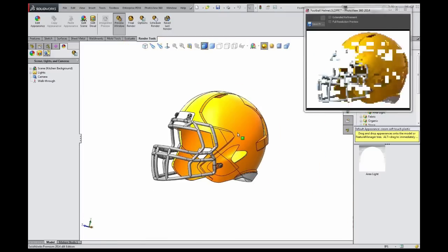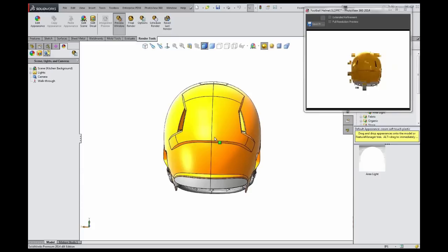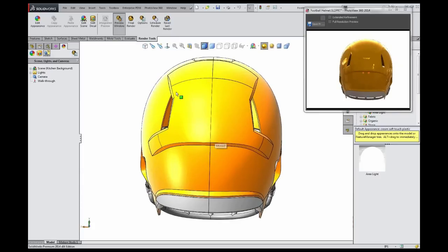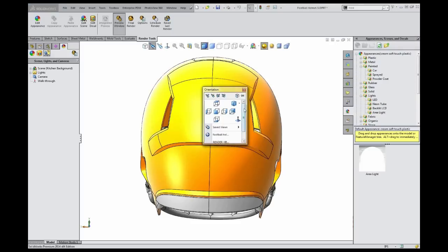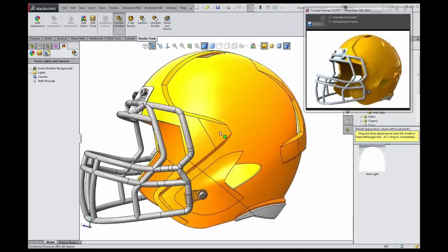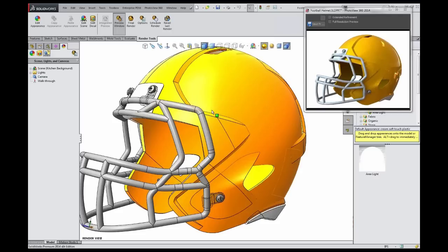I'm going to turn off perspective and rotate this around to like the back view. Now if I wanted to, I could select that view once again by bringing up the View Orientation dialog box and selecting Render View. It's going to turn on perspective to the exact value that I had set as far as how drastic it was being applied, and it even changes the camera orientation as well. So there's absolutely nothing wrong with, rather than creating a camera, just creating a named view. It's quite a bit easier interface-wise because you're just rotating the model around to where it looks good.